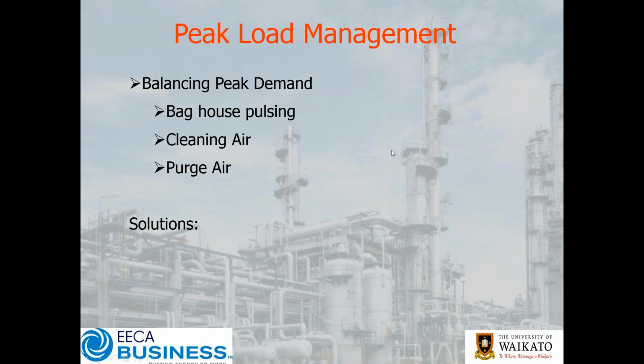Well, obviously one of the big risks with the baghouse pulsing is if your Goyen valve that's used to generate the pulse actually sticks open, which can happen fairly regularly. It's very easy for those things to drain your air system very quickly. So you want to have additional storage at the point of use and sort of non-return systems in place so we can't drain the whole system. There's some really good products on the market now where you can have cut-off switches. If the pressure drops to a certain point, it will then isolate the rest of the system, and then obviously you have an alarm on your baghouse, and then you need to go and fix it.